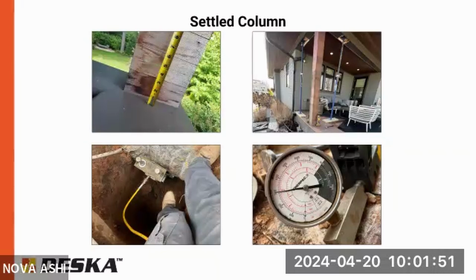But the structural polyurethane foam is not typically used to support anything other than a slab or maybe a thickened slab or some steps. It's not meant to support a structure above it as well. And usually it's pretty light though. So, I mean, that is a potential way to do it. Outside of that, you could install helical piers. That would definitely be an option.